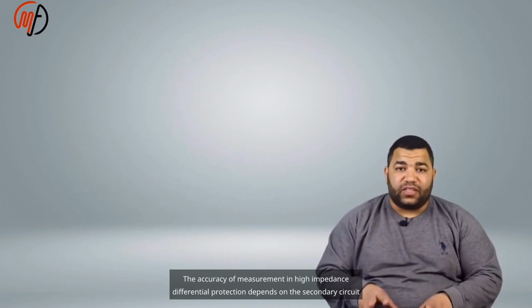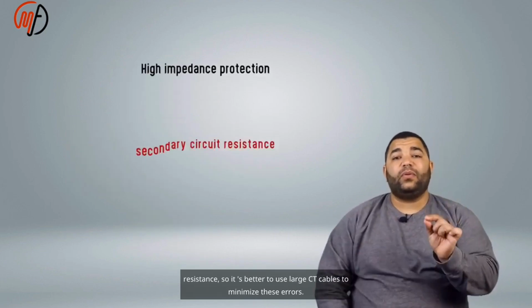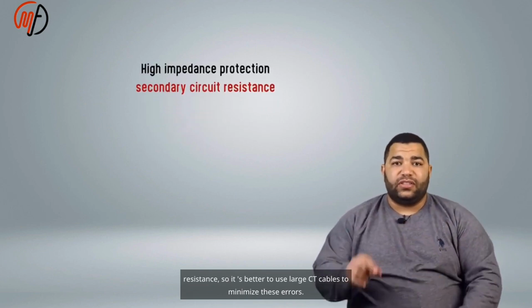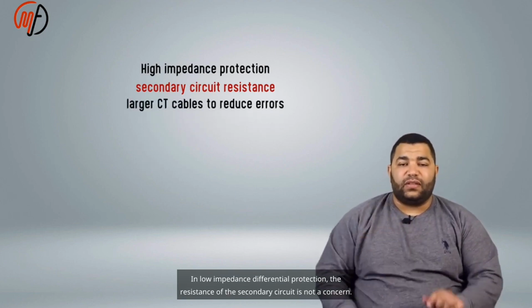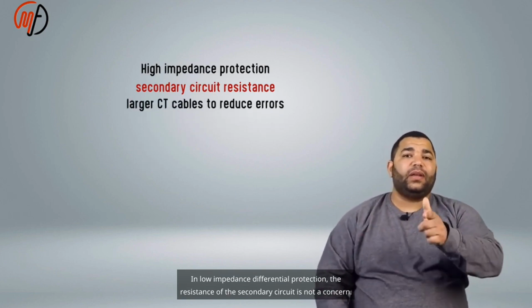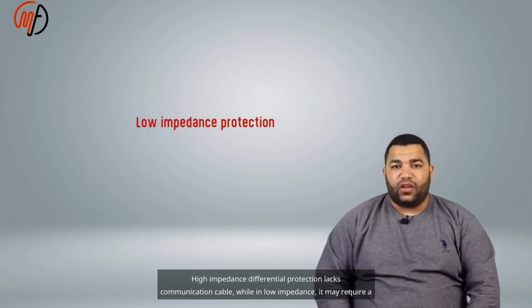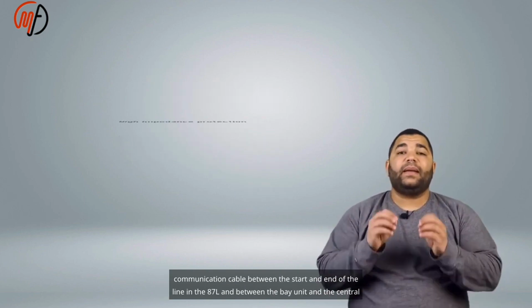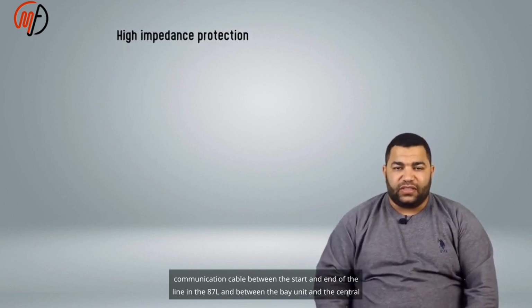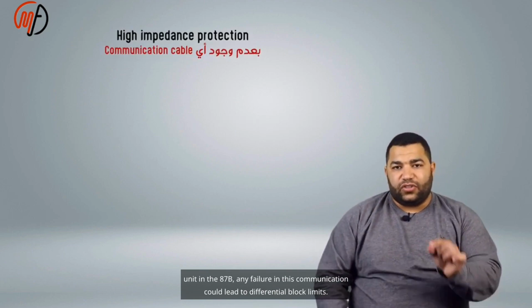The accuracy of measurement in high impedance differential protection depends on the secondary circuit resistance, so it's better to use large CT cables to minimize these errors. In low impedance differential protection, the resistance of the secondary circuit is not a concern. High impedance differential protection lacks a communication cable, while in low impedance, it may require a communication cable between the start and end of the line, the 87L, and between the bay unit and the central unit in the 87B. Any failure in this communication could lead to a differential block limit.